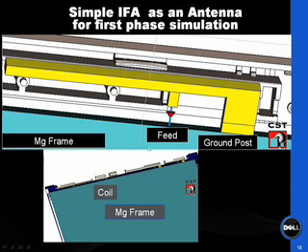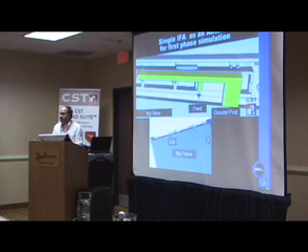And this feed and the ground post, you can model this feed like one inductor, and this ground post one inductor. So two inductors placed side by side act like a secondary transformer. So the distance between them can control the matching, how well the antenna is matched. And the distance between the magnesium frame and the radiator controls the performance. Usually 10 mm is good, but when you're working with mechanical and ID people, where they are crushing the dimensions, even getting 7 mm is very hard.